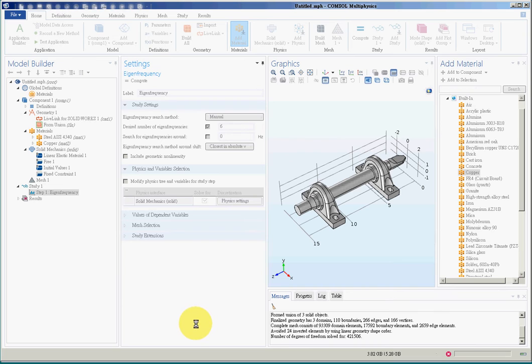Actually, in COMSOL, you can also draw the model here in the Build All geometry part. There are 3 ways you can generate geometry. The first is to build inside COMSOL. The second is to import from CAD system softwares, for example, IGES files or parametric files, imported in, for example, IGES format.